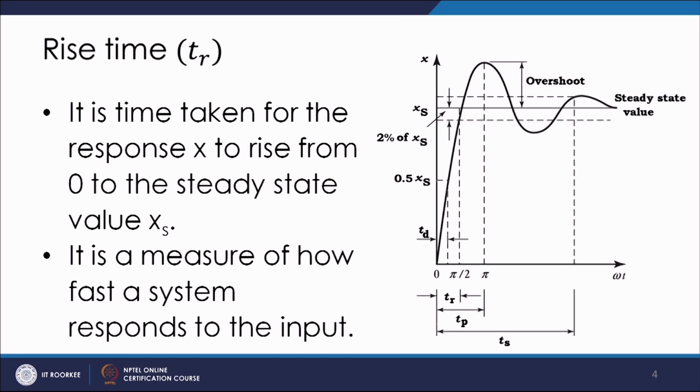For an overdamped system, T R is considered as the time for the response to rise from some percentage of the steady state value, say from 10% to 90%.